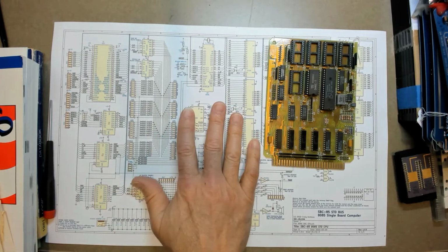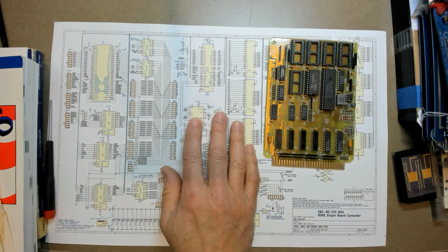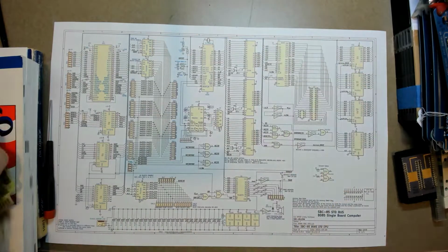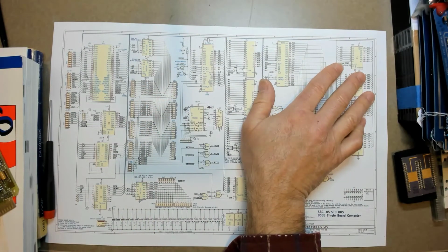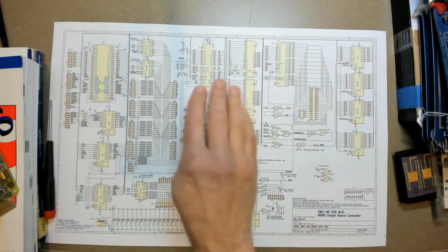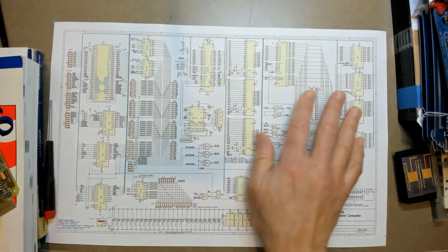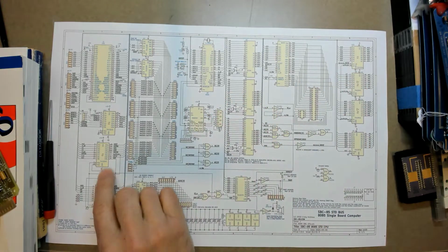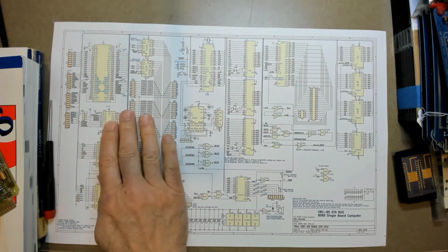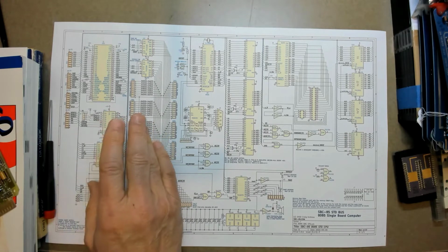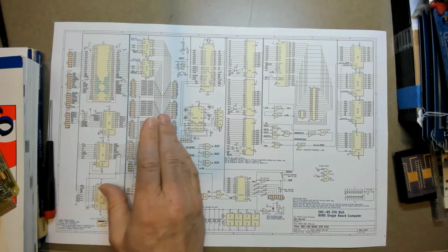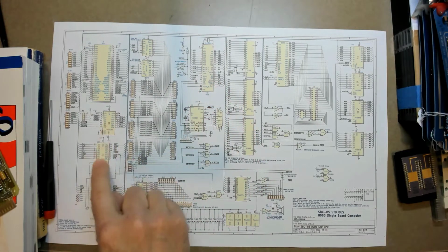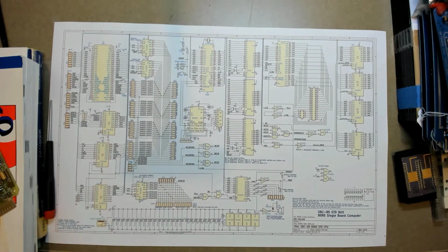That means that this card has two primary modes of operation. The first is where this processor card is driving all of the bus signals onto the backplane. And the second is where the processor is stopped and it's released all of the bus signals. And what that means is that most of the signals controlled by this card must be tri-stated onto the bus. That's to say, in addition to the card being able to drive the signal high or low, it can place the line into the third state, which essentially disconnects the line from the bus. And that, of course, is the tri-state.